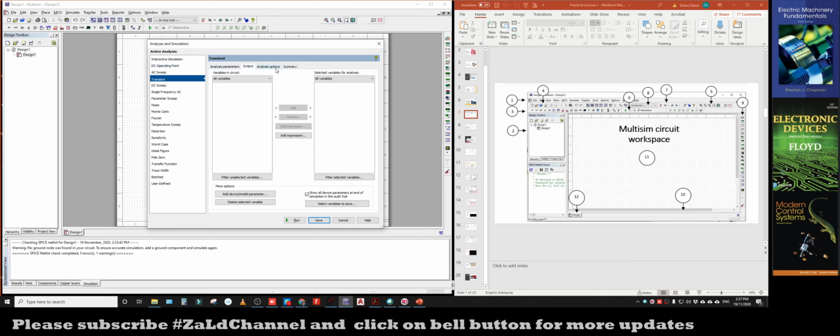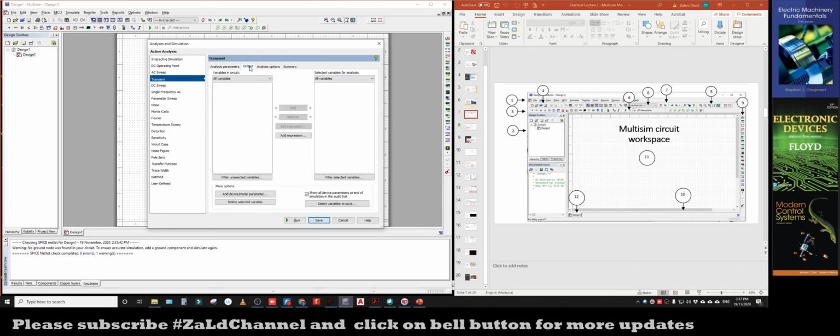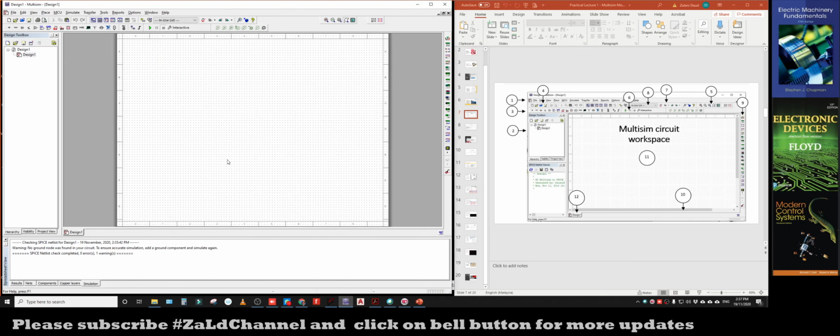We have another tab here, which is the output tab, and then summary. So basically, for the transient simulation, for example here, what we need to do later is to put the start time and stop time of the simulation, and then the output variable we would like to observe, right? For example, at the output, we would like to observe the output voltage, so we can select the voltage, right? So that is about number 6, which is the button that represents the simulation, which is this one. And then number 7,